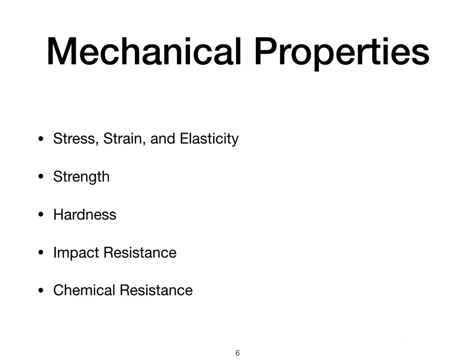It is very important to understand that while glass is elastic in nature on a microscopic level, it is also a very stiff material on the macroscopic scale. This means that for typical stresses applied to glass, the resulting strain is very small. But knowledge of Young's modulus can be very useful in predicting the strength or impact resistance of a glass piece. Say you are designing a lens that needs to withstand large pressure without breaking, such as an exterior submarine light.